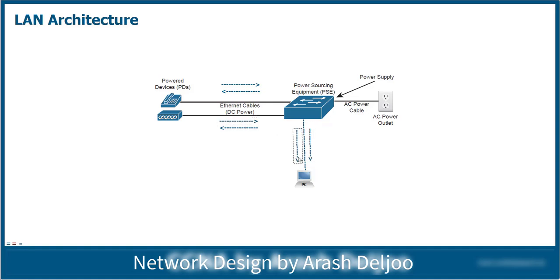If the negotiation result is that this is a PD, a powered device, you can apply the power to that device. The question is how the switch can negotiate with the other side. Let me emphasize that this is related to, for example, level 1 signaling, but also to the auto-negotiation features of the Ethernet interfaces, with which we can talk about the PoE capability with the other device.